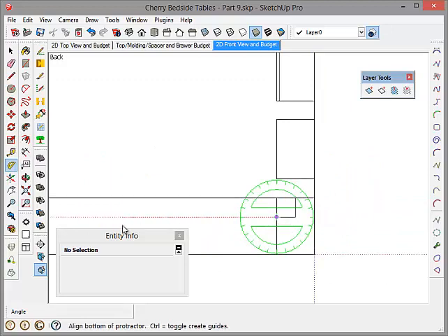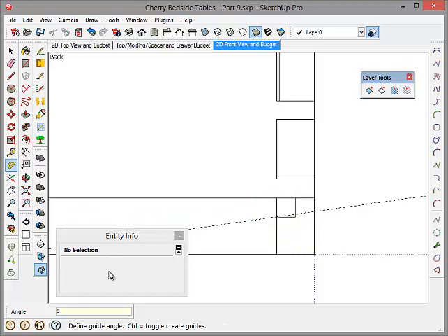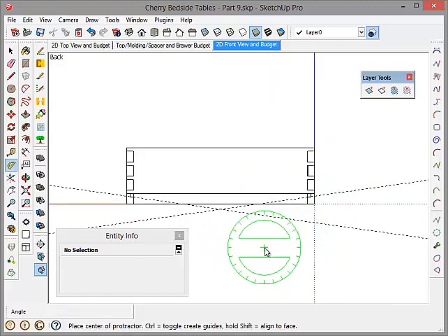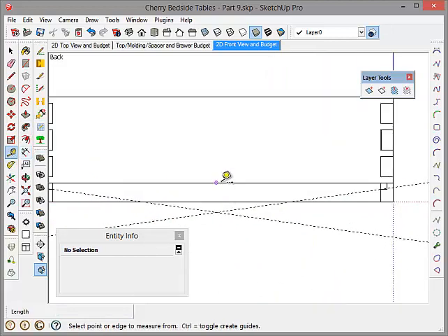Come out along the red axis and then down 8 degrees. And the other thing I'm going to do, take an edge here on the back. This is the bottom of the back. Come down along the blue a 1/2 inch. That represents the thickness of the bottom.